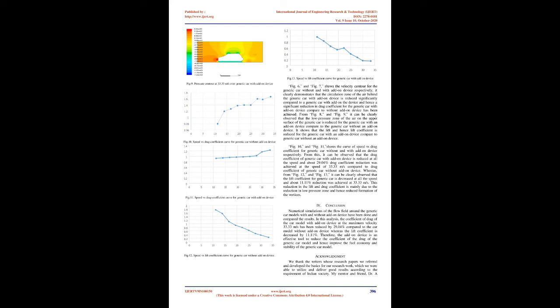D. Solver selection and solution setup. An accurate solution can be achieved by using a proper solver to perform the simulation. Generally, the pressure-based solver is used for incompressible flow, whereas the density-based solver is used for compressible flow. The basic difference between the two solvers is how the energy and momentum equations are coupled together. For example, the pressure-based solver solves the energy and momentum equations in a decoupled manner using the SIMPLE algorithm, whereas the density-based solver solves the energy and momentum equations in a coupled manner.